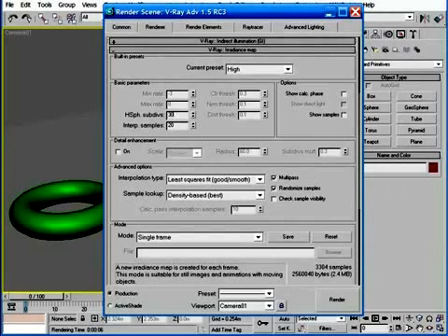If you do find problems such as splotches, then you might want to experiment with small increases of this value, but you might want to avoid values above 50 because it can really increase your render times at the benefit of very little gain in quality. And likewise, values below 20 should really be avoided because the savings you're going to find in render times are not worth the great loss in quality you're going to get from lowering this value.